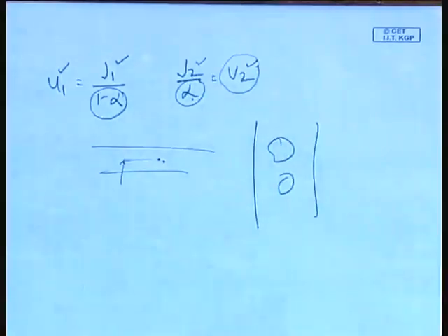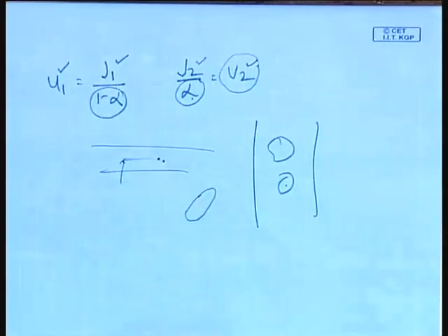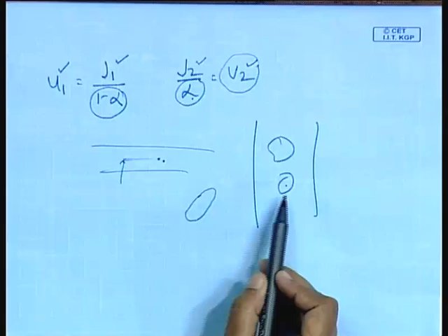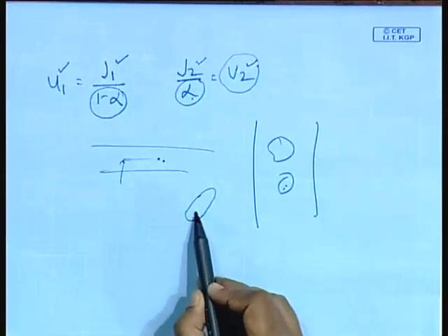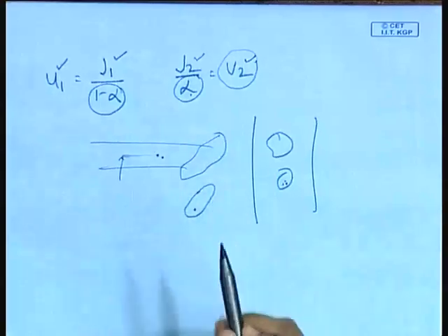Getting good photographs is definitely a challenge, particularly when the flow velocity is very high, everything is oscillating and there are small problems which you will not realize. Suppose even if it is bubbly flow, okay, with a large number of bubbles. First thing is, when you take the photograph, you will take it from an angle. So, definitely this bubble, this shape will become deformed in your photograph. Okay. So, there has to be a calibration to convert this shape to this shape, and then this shape maybe will become something of this sort.